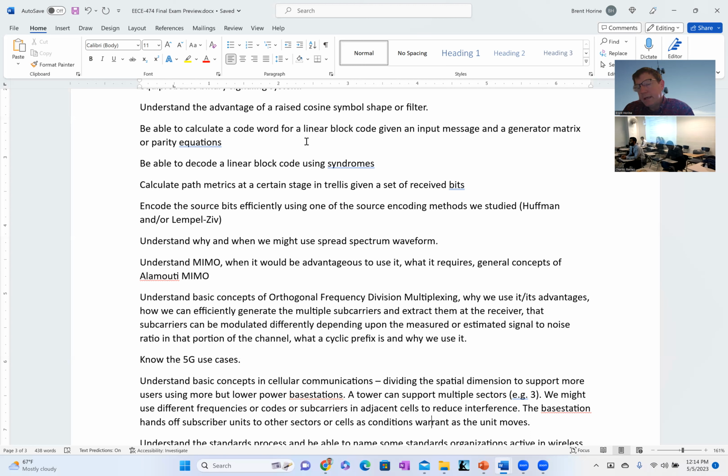So the most likely error is that you had 1 bit error out of your code word, right? So if our code word is 7 bits long, and we have input bits of 4, our overall code word is 7, and therefore we have 3 parity bits, right?